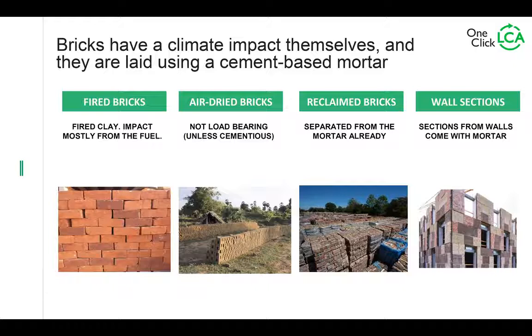But what's been recently done, and I encourage everybody to consider, is that the brick wall can also be sawn in sections with the existing mortar. So just take 1 meter by 1 meter sections and pile them into your new building, and you have far less mortar demand and far less cost. I would think a very advantageous setup all in all.